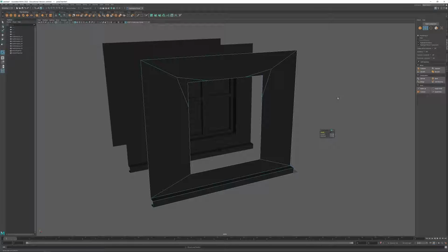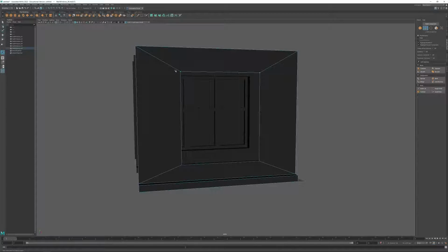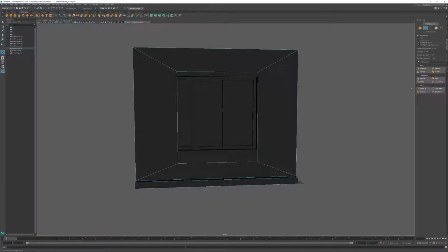Yeah, it looks like all of the tools that we have at our disposal are going to split this in a way that isn't going to be ideal. So we'll use the tools that we have and we'll make do. I will go and bevel this. Once the bevel is done, I will select the corner vertices and I'll scale them in and move them down until we've got a little bit more of that arch here.